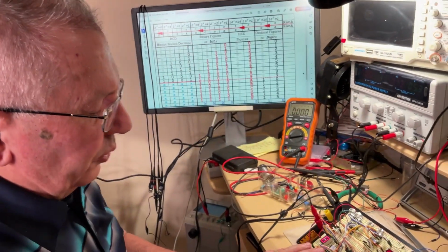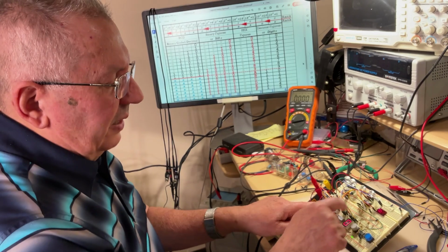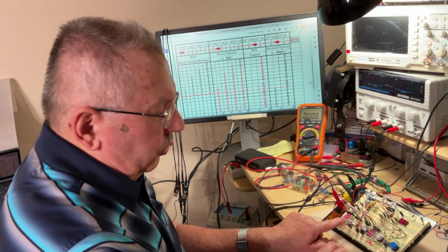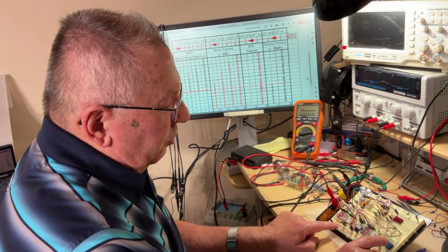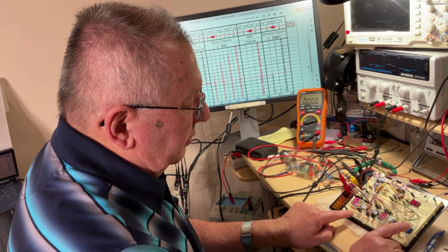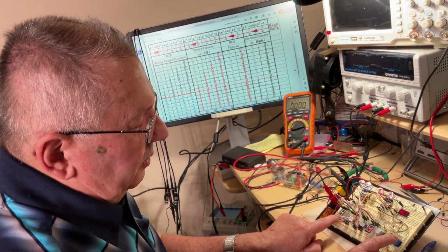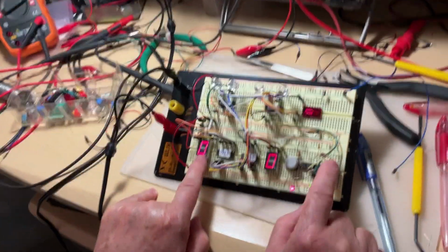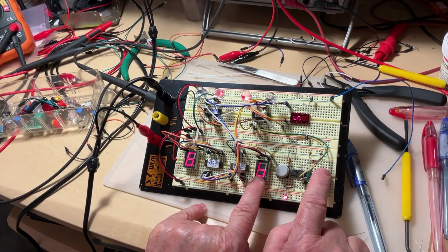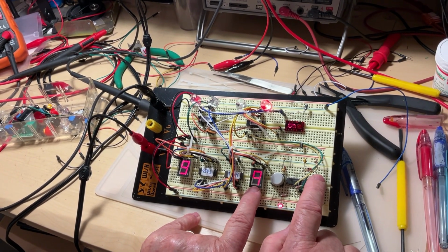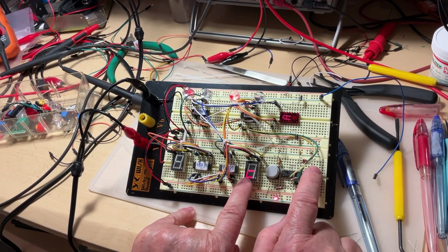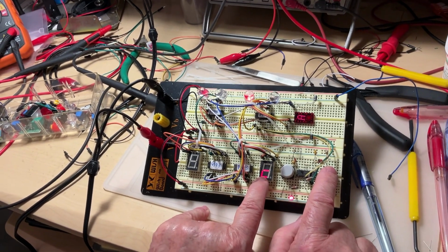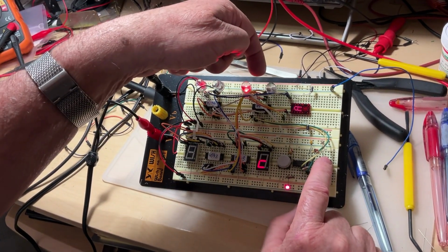Now, here is the point. I'm saying that these three displays show different things. This one here only shows the BCD code, meaning whatever I'm counting, in the moment I'm going over 9, the display remains blank, up to 15, and then restarts from 0. This one displays something after 9. But you have to recognize these particular shapes, because on one display it's not possible to put the number 10, and this is 10. How do we know it is 10? Because it's 1010 in binary.